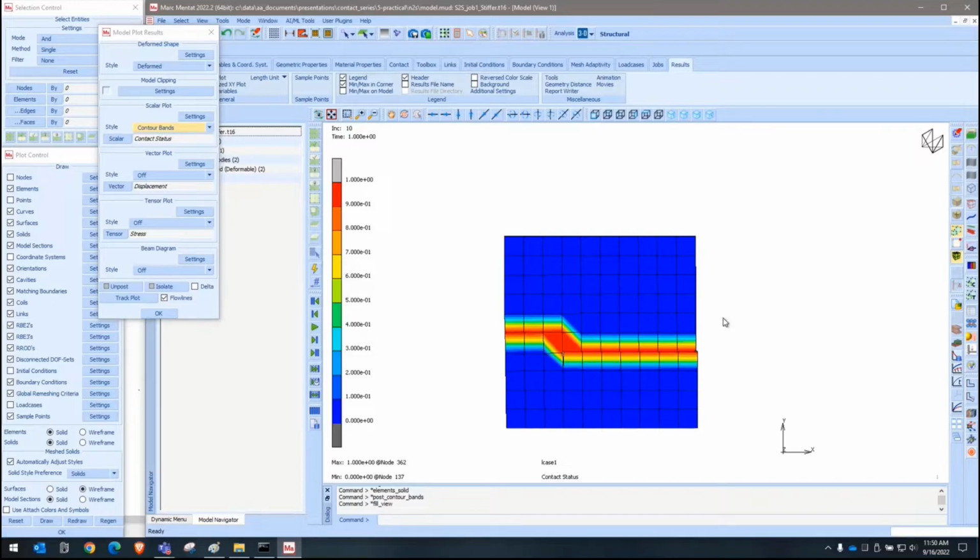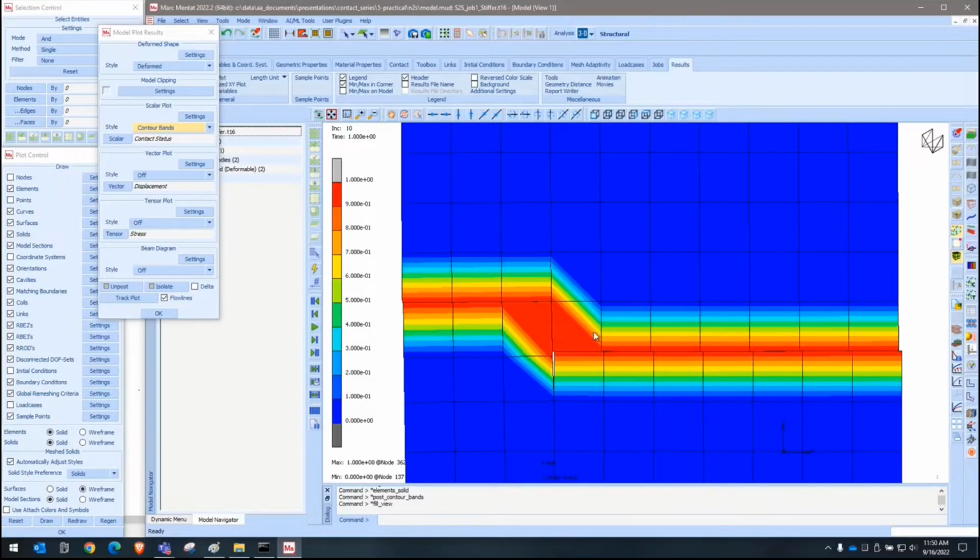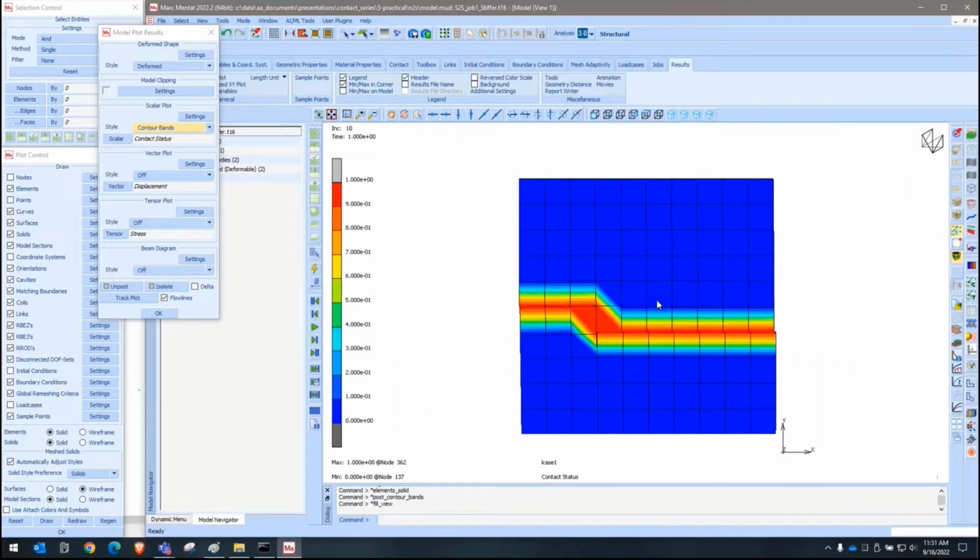The segment to segment, on the other hand, has contact conditions that are much easier and much clearer to set up. So it's easier to get a segment to segment model in theory running. In practice, you may have issues with that penalty stiffness. It's not something that works really well in all models. If it works, you usually get a decent answer. You may just need to tighten up that stiffness effectively. So let's talk about when that stiffness is enough or not enough.